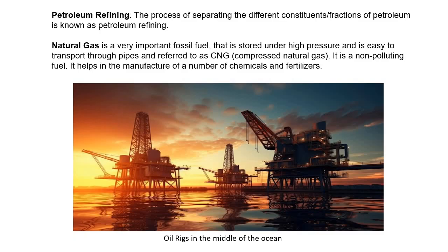Major refining stages include distillation, conversion or upgrading, and desulfurization. Distillation, the first stage in crude processing, is known as distillation or fractionation. In this process, the crude oil, which is a mixture of many hydrocarbons, is boiled and recondensed to separate the crude oil into components based on ranges of boiling points.